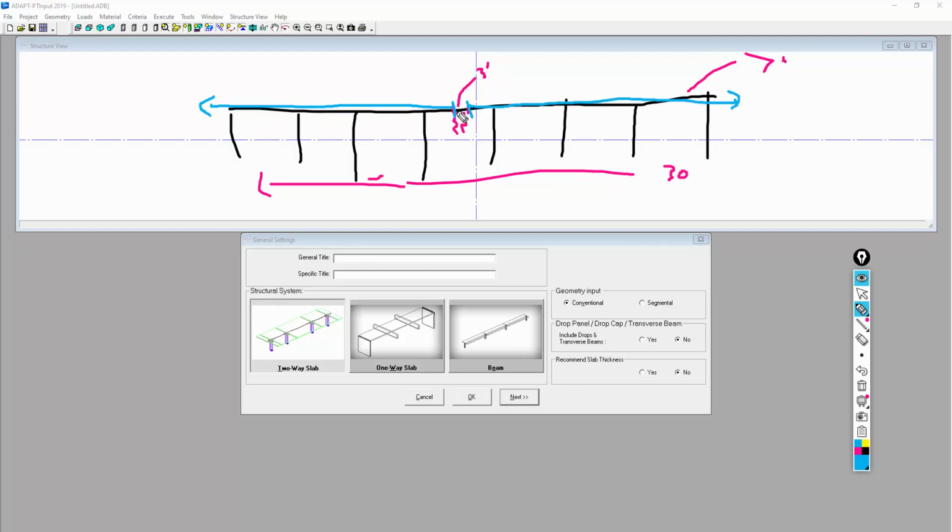And after those two tendons or sets of tendons along the pour strip are stressed, we come back several days later and we pour this back. And we have reinforcement passing through here that's going to take care maybe of the flexural demand across this location. And so we're going to assume that for our model, we're really just representing the final stage of this strip, the as-built condition of the strip. And we're capturing that through this particular model.